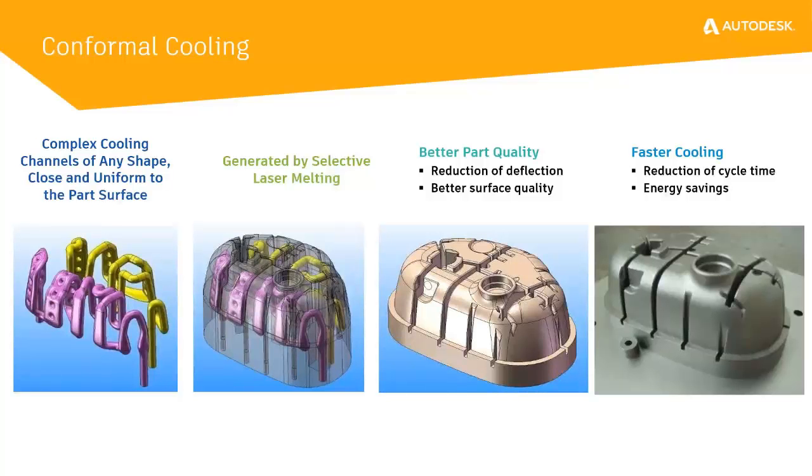Leveraging Moldflow as a simulation tool is a great way to help when justifying the insert cost versus the expected cycle time savings. Moldflow can also show the additional part quality benefits, like the reduction in shear stress or warpage.